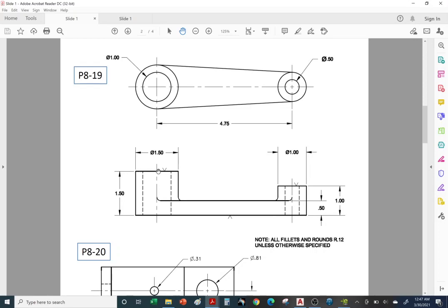So this is also going to have a rough surface, so you come in and machine it off. Same thing with this one. It'll have a rough surface, and at the bottom, a rough surface. So you come in and just machine off a nice planar surface, a nice smooth surface, so it can easily mate up with its other parts, whether it's a vehicle or another assembly other than a vehicle.